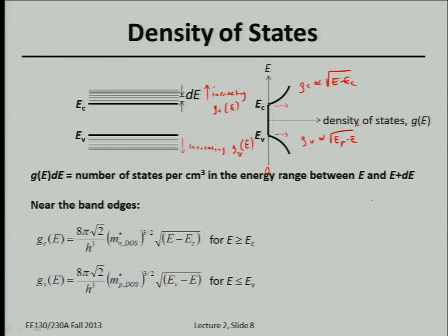The spacing between these allowed energy states is influenced when you bring multiple atoms together, and the potential influence of the atoms depends on the effective mass of the electrons. The lighter the effective mass, the more energy level splitting you'll see. If you have effectively lighter electrons, you'll have energy levels that are spaced further apart. This is like the quantization effect. That's why the density of states also has a weak dependence on the effective mass.